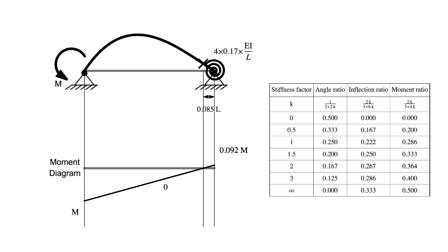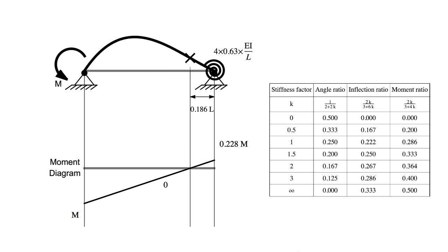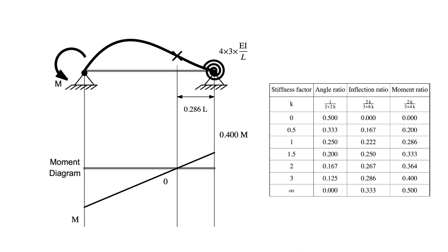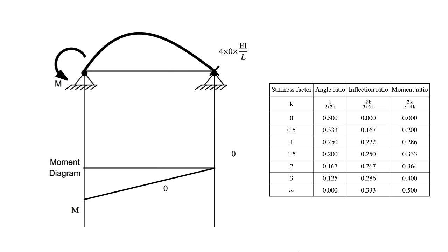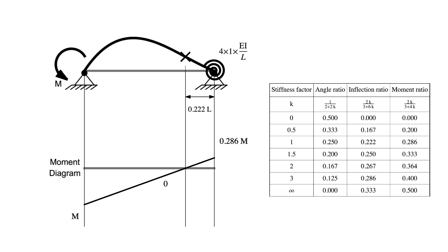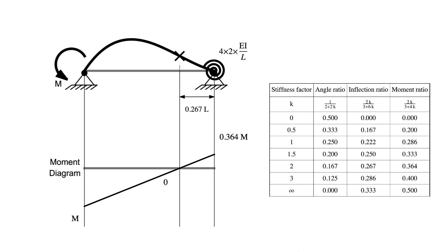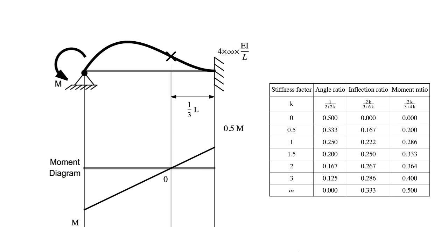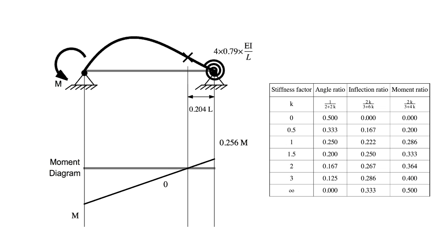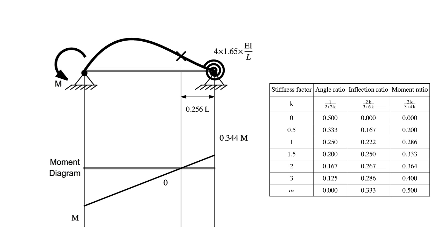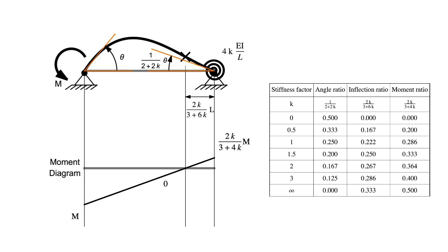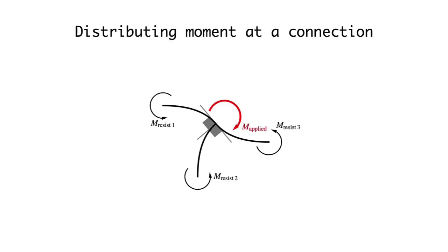If we look at the deformation and bending moment diagrams for varying values of the rotary stiffness factor, we can visually notice rapid change in values when the stiffness factor varies between 0 and 1, followed by a rather slow change afterwards. This is important because it suggests that if our basic approach in approximate analysis is to estimate the stiffness factors, then we expect good results because calculated values are not too sensitive on the rotary stiffness factor. We only need to be careful to distinguish between zero stiffness and non-zero stiffness at a connection.